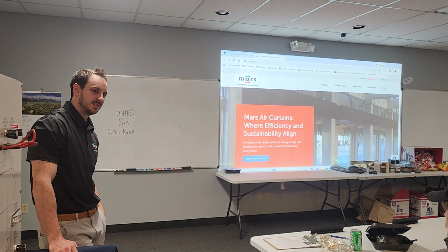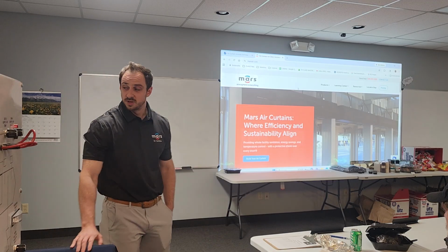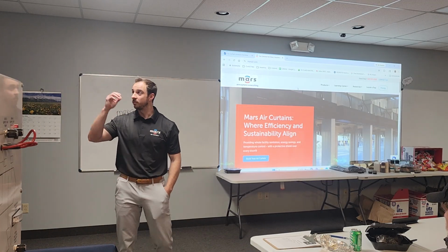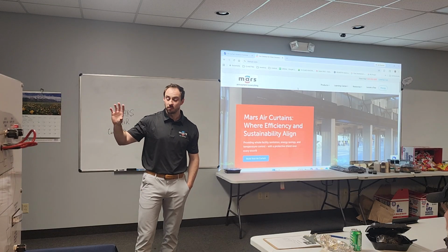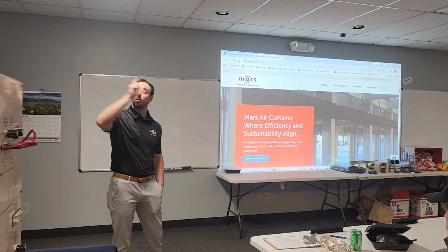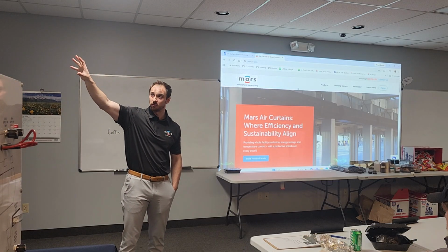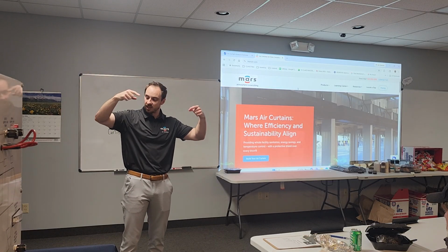How is that air aimed? Like the direction of it. Yes. Typically the best coverage is straight down. The only way you would have to modify that is if you're pulling it off the wall, like with a bracket, or if it's hang mounted. If it's not flush over the door, you just want to angle it.